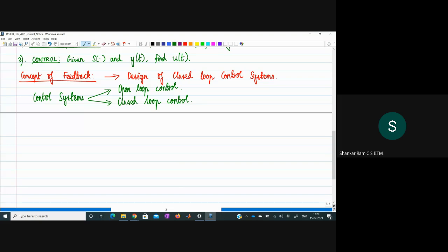Let us say after I install the fan, I attach some light fixture or some other unit to the fan rotating element. Now the inertia of the mechanical components has increased or changed. If I provide the same electrical input by the same regulator, I am not going to get the speed for which the fan has been designed.